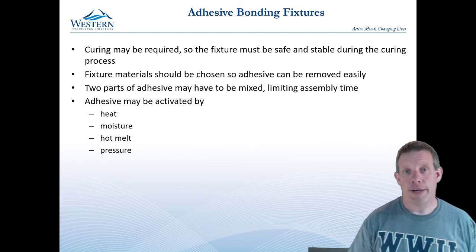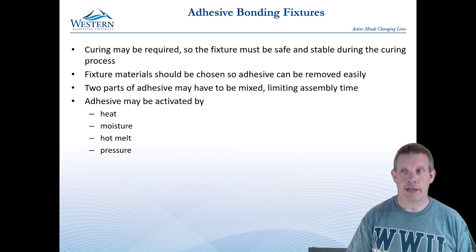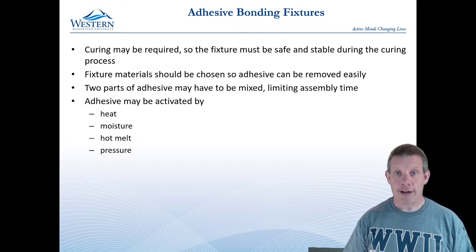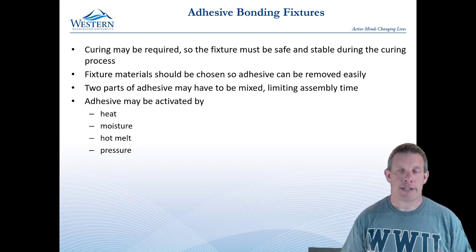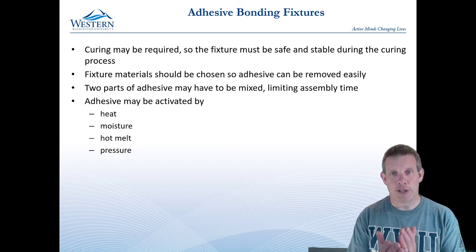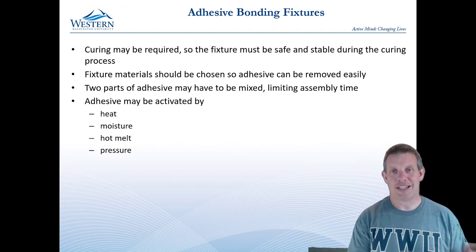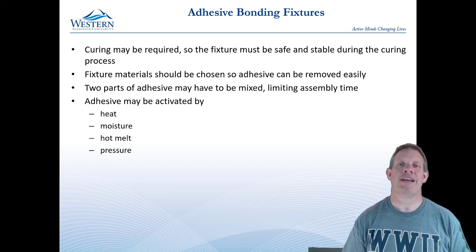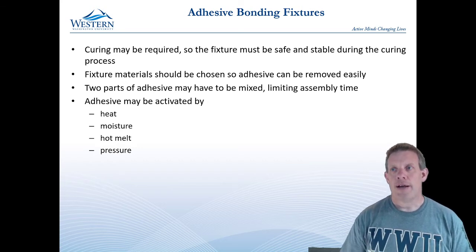So when we're talking about adhesives, one of the big challenges is that we often have to allow time for curing. And so the fixture has to be able to grab something and hold it for an amount of time. But that also means that the fixture often has to be low enough cost that we can build multiple fixtures. It typically does not work to build one fixture, take it out of production for 3 hours while something cures, or overnight if it's an oven cure, and then bring it back and put one more part in. So that often sets a cost threshold.